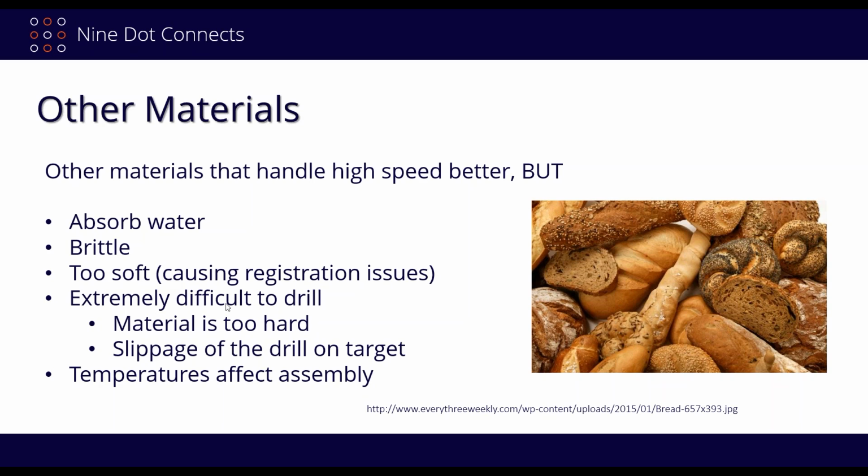Some of the stuff is really brutal to drill. Some of the materials are very, very hard, so you can drill them, but you're going to pay additional tooling costs because you have to go through more drills. There's also a bit of slippage. Some of the stuff is really slick, with something like an enamel coating on it. It's a very smooth coating, so there's a little slippage on the drill when it first tries to penetrate the material, and you may not be as on target as you want to be.